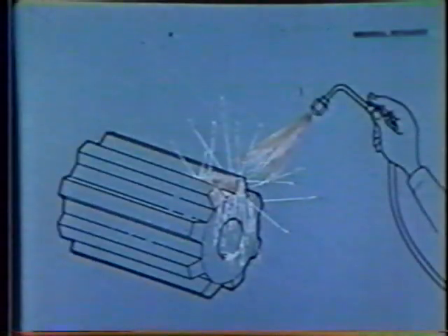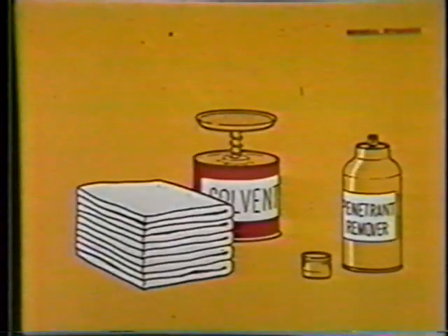Using hydrophilic scrubbers, post-emulsified penetrants are emulsified and removed in the same manner as water washable penetrants. Washing action stops when spray is stopped. Using solvent removers, penetrant is usually removed by first wiping with a clean, lint-free towel, then following with another towel slightly moistened with remover. Solvent should not be applied directly to the specimen.